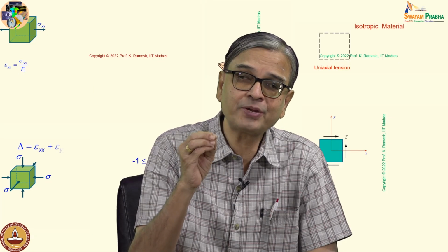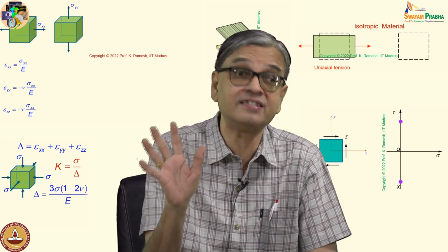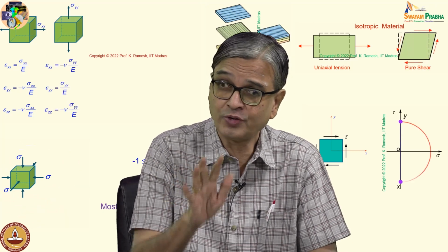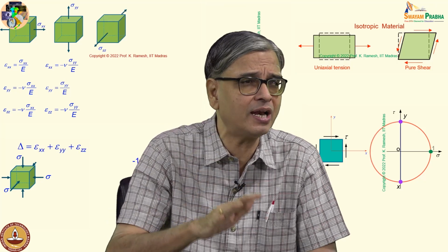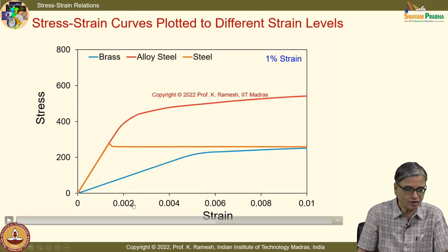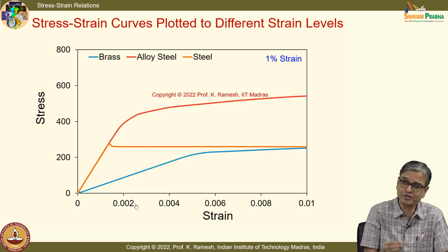So what you will have to appreciate is at 0.2% strain the material yields. It's a very, very important knowledge. Never forget this. So we operate at a very, very small level of deformation. I can say it as 0.2% strain, or I can call it as 0.002. I can also say 2000 micro strain. So whichever way it is mentioned, you should be able to appreciate this.